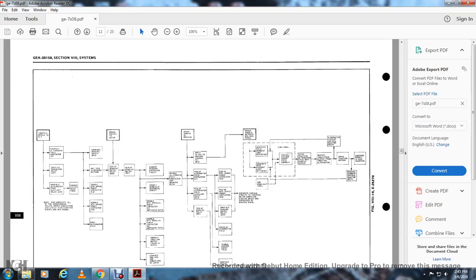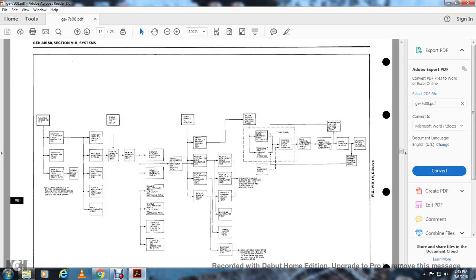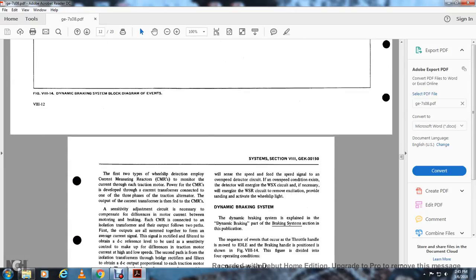Now back to the pickup alternator field contactor, pickup field with series of the contactors, pickup motor series of the power contactors, dropout dynamic braking switch relay, and the energizing alternator field relay. Alternator field auxiliary relay goes to the enabled exciter shunt field, and picking up the brake relay drops out the engine running relay.